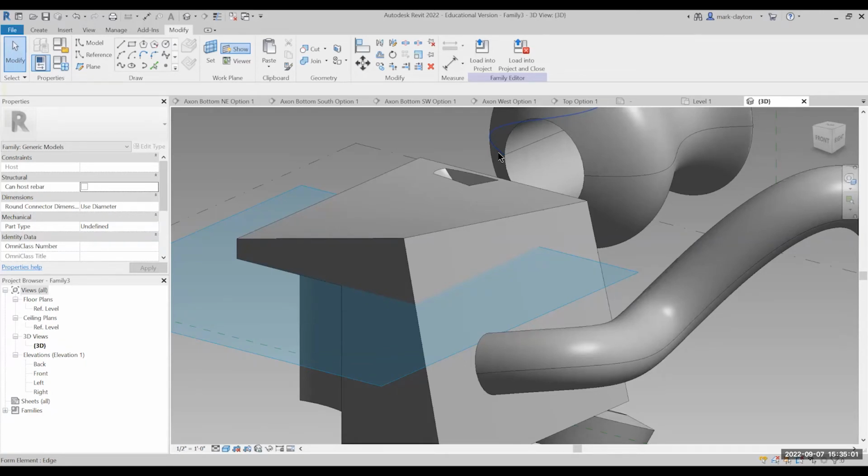And I'd suggest you make them in 4 different files instead of copying them from one to another, all in the same file. You can save as and take your first one and modify it, and that becomes your second, and save as and become the third and modify it, and so on. But it's easier in Revit to work with each version in a different file.